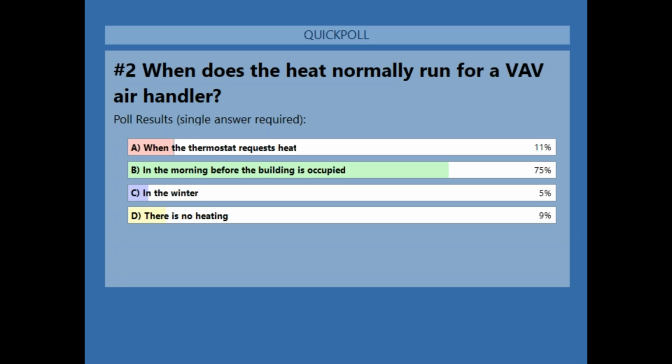If I have a very high amount of outside air requirements for my space, I'm going to want to think about designing it to have a tempering mode like that, which means my air handler supplier or my rooftop supplier may need to order something different for me, and then my controls contractor will need to program something different for me. But if you just say VAV out of the box, you're not going to have any type of heating up to 55.